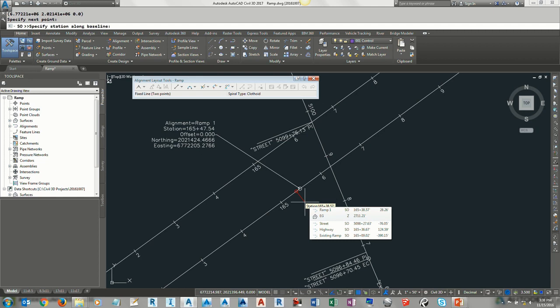And you see that it has some northing easting there, which means you did get that point. Good. From this point, the Highway Design Manual criteria from Caltrans again is that for this length, in 300 feet, I need to deviate 6 more feet. So if that point was 12 feet away on the edge of travel way, the next point, if I use this alignment, should be 18 feet away and 300 feet.